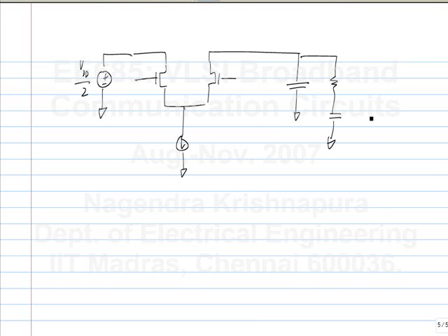Okay, so this is the loop filter. Similarly, you have a PMOS counterpart on top. Okay, now this is controlled by the up signal. And I don't imply that these will go from 0 to VDD. There may not be CMOS logic levels. You have to see what is the right logic level to switch this differential pair.